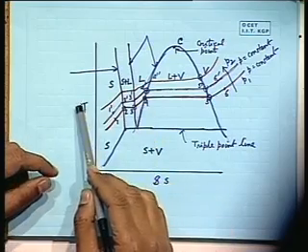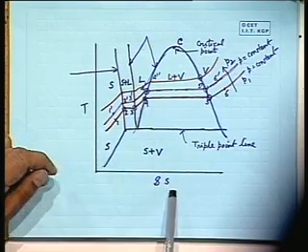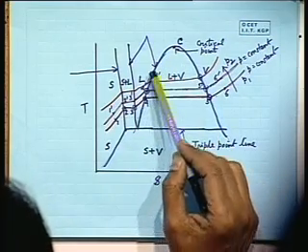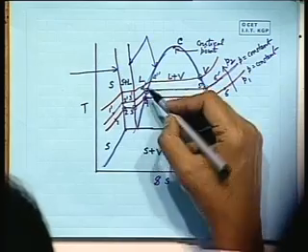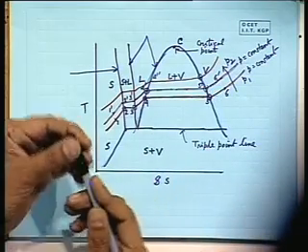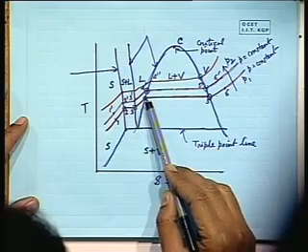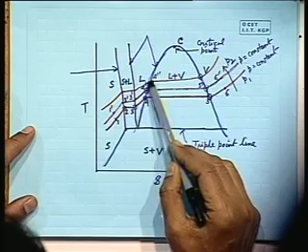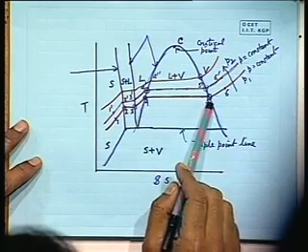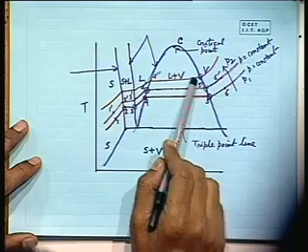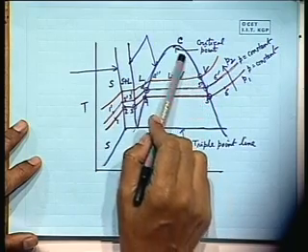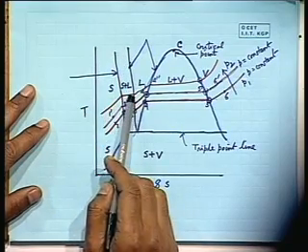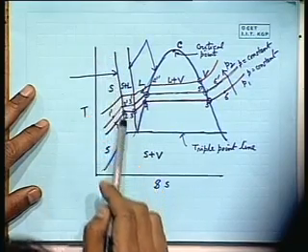So you see again that in the TS plot, the temperature and specific entropy, the plot is like this. This is the vapor dome. Typically these are the saturated liquid lines for boiling or vaporization. This is the locus of points, which we designated as point 4, the saturated liquid state for vaporization. Similarly, this is the locus of saturated vapor points, known as the vapor line, and this is similarly the saturated liquid line for solidification, and this is the saturated solid line for melting.